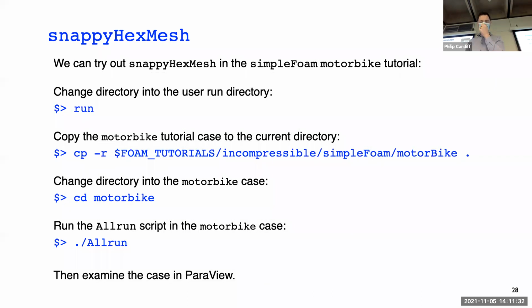So an example of how to do this. In, I think, next week's tutorial, the last weekly tutorial, we're going to do it for the action car again. So the same week 6 tutorial, where we do this action car, this toy matchbox car, and do a CFD analysis of external aerodynamics over that. We basically just do the same thing, to see how you do that with snappy hex mesh and how that's different. There is a built-in tutorial in OpenFOAM called Motorbike, and there's a picture of it.